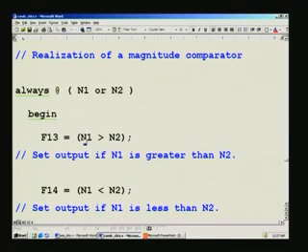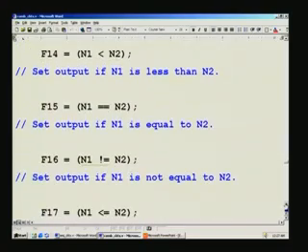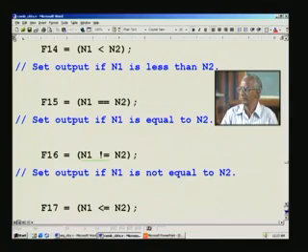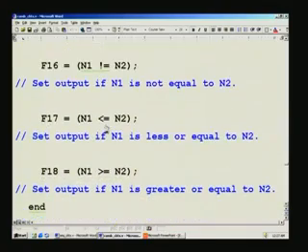Braces are always easy to read, so make it a habit to use braces freely. And again, not equal to and less or equal to. In an always block you use that one. You should distinguish the difference between that. Here it has a different meaning. It means precisely less or equal to. In an always block, the non-blocking statement, as it is called, is mere equal to.